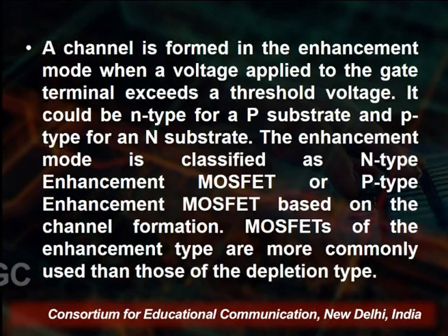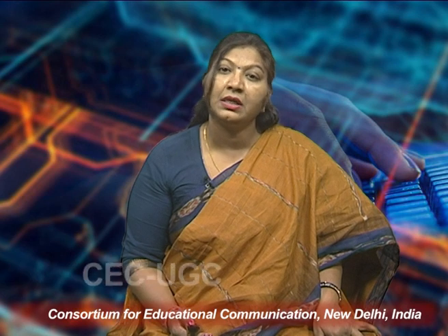So, in the enhancement mode, we further classify into the N-type enhancement mode, that is the N MOSFET, and second is the P-type enhancement mode, that is the P MOSFET, based on the channel formation. MOSFETs of the enhancement type are more commonly used than those of the depletion type. So, we can use it.